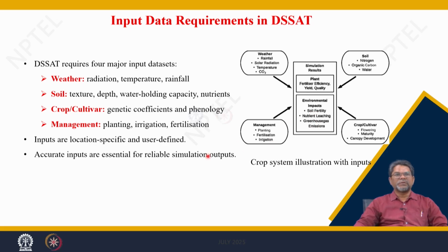So, the inputs are location specific and user defined. Accurate inputs are essential for reliable simulation of the output. Before that also, as we discussed in some classes, you need to know model calibration and validation, how you must calibrate the model and validate the model for the local conditions where you are applying this model.